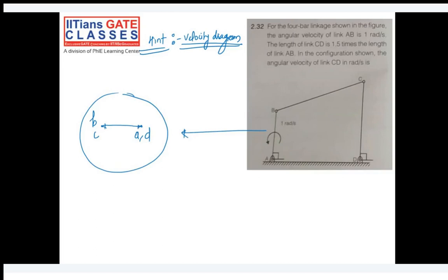Yeah. So we have already studied, if you remember, whenever two links are parallel to each other in a 4-bar chain, the velocity triangle will be a straight line. Correct? So now, what is the velocity of link AB? The velocity of link AB, as I have shown here, is A to B, that is L2 omega 2. This is the first link, second link, third link, and fourth link. The velocity of link AB is link 2 basically. And the velocity of link 3 is 0, correct?